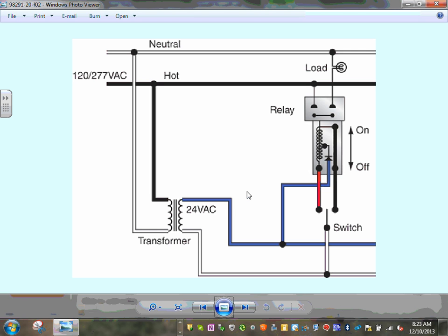When you take the switch to the on position, which is the black, you energize this coil right here, and this coil will push these contacts to close. Now the light is on. And there's a spring that comes with it. The electrical energy pushes the contacts closed, and a spring holds it shut. When you want to open it, guys, there's another coil that you energize. That coil will overcome the spring and open it, and another spring will hold it open.